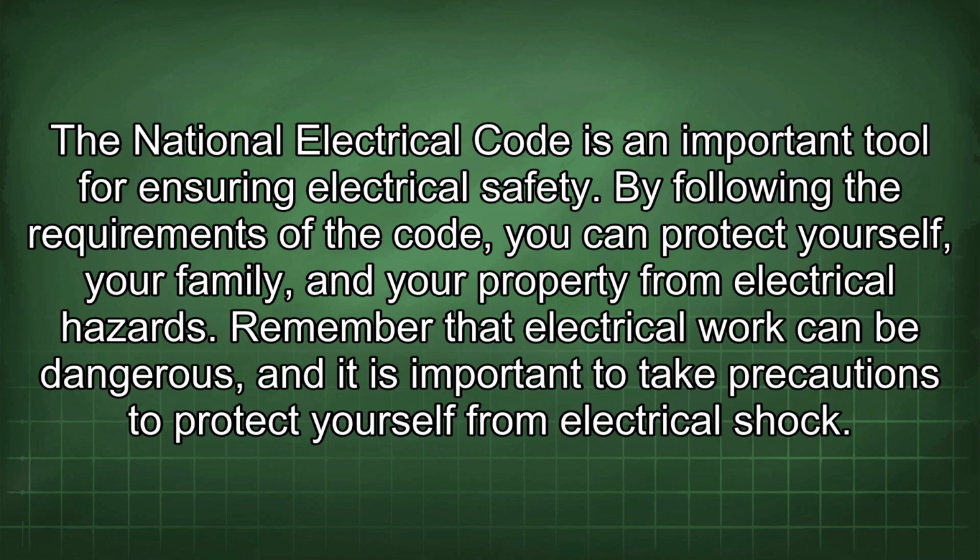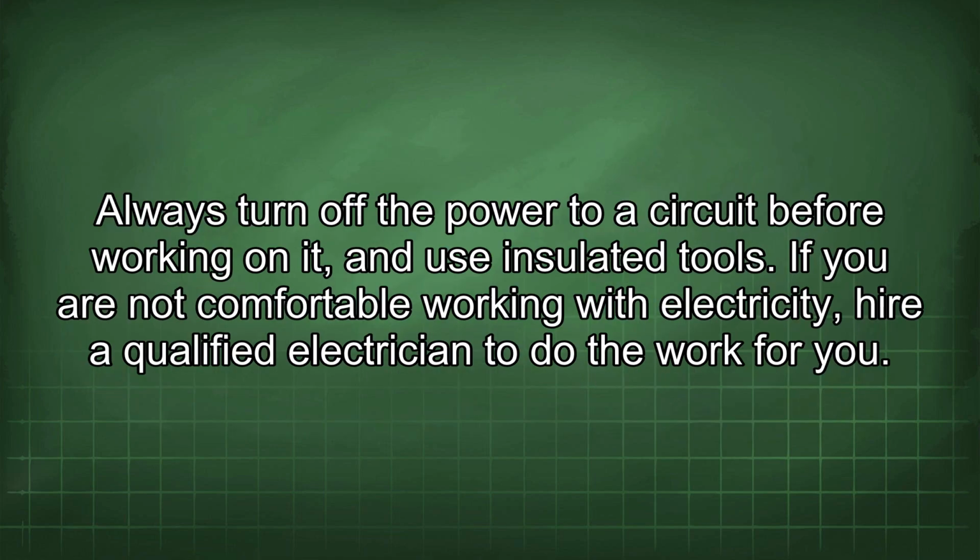Remember that electrical work can be dangerous, and it is important to take precautions to protect yourself from electrical shock. Always turn off the power to a circuit before working on it, and use insulated tools. If you are not comfortable working with electricity, hire a qualified electrician to do the work for you.